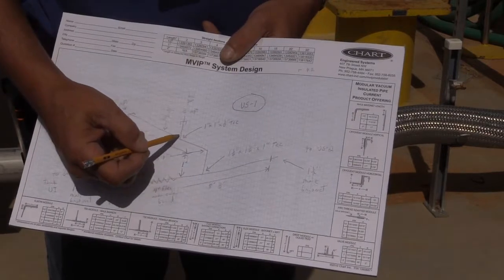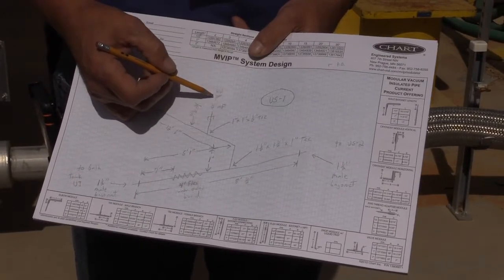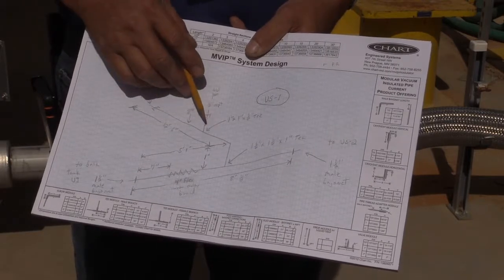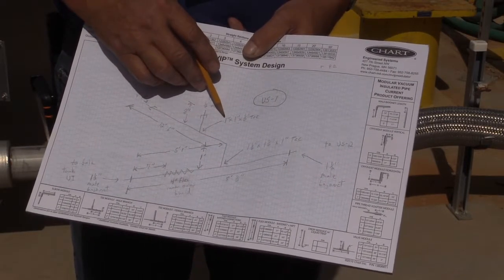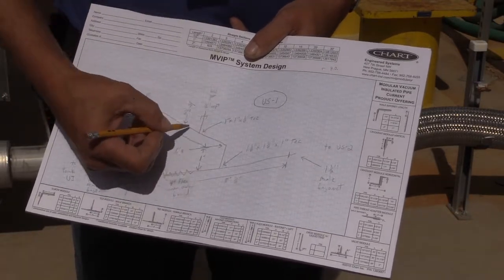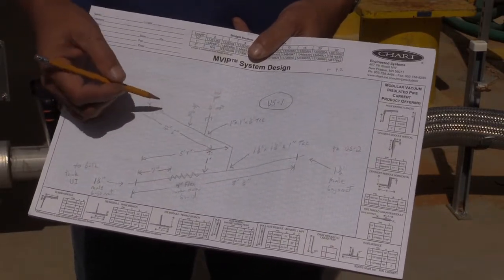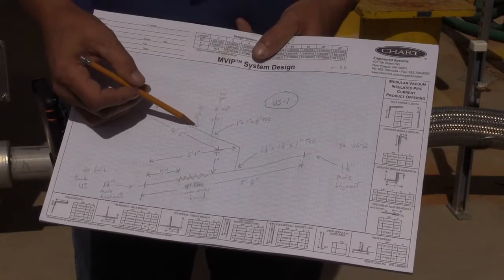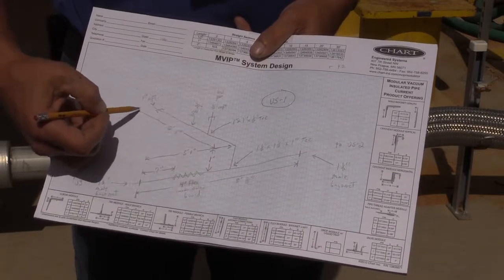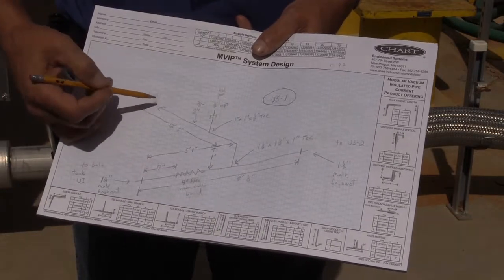Same thing happens here where we take a 90 and we come over to this riser where we're going to put a relief valve. You see that it's clearly labeled relief valve with a 1/2 inch MPT connection on it. You also see the denotation that we have 1 inch by 1 inch by a 1/2 inch T, meaning that the header is 1 inch and we're going to come up as a 1/2 inch to supply the relief valve. You also see that I've labeled distance in all these things for heights and overall lengths again, so we understand exactly what needs to be built.